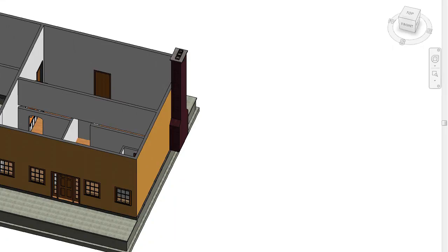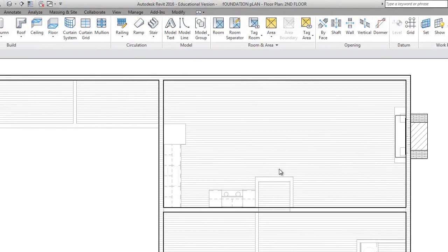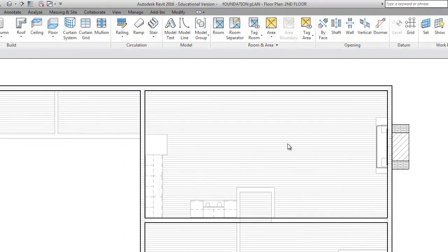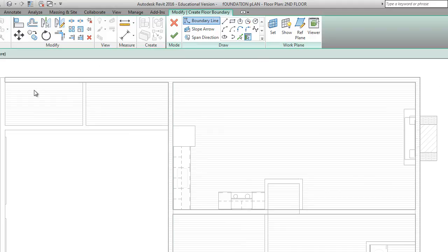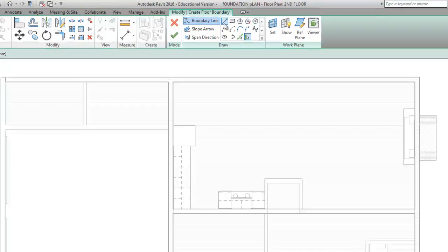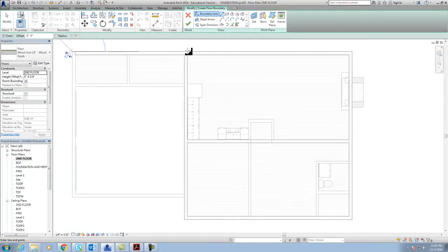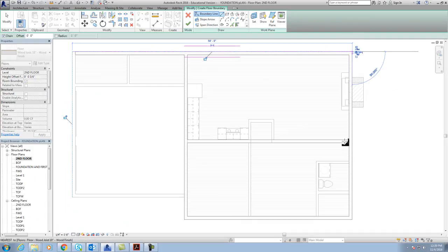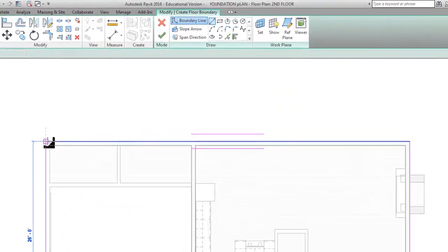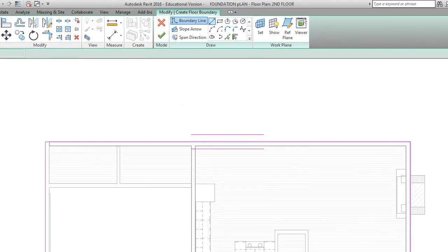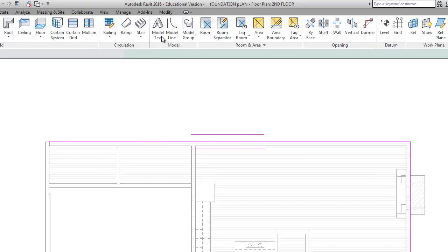And now, with that said, we'll go back in here and we'll go ahead and put our floor in for this. And to put your floor in, architecture, go over here to floor. And I'm just going to put a floor throughout this whole thing, okay? I'm just going to start here and just bring it there, there, there, there, all the way to there. And then make sure it's 3/4 offset and finish.